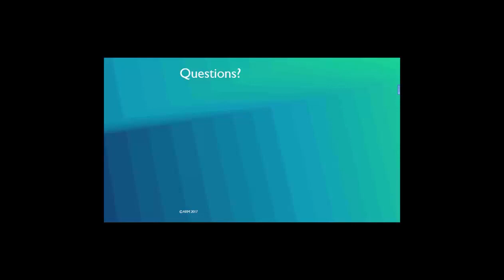Yeah, it's a very good question. So yes, you can split the problem up, kind of standard formal assume-guarantee kind of method. As you say, you can fake out the intermediate state between two instructions with a kind of handwritten piece of prediction logic. And then you can have a different configuration where you forcibly turn off the processor's ability to fuse that instruction. And then you verify that your handwritten model of the intermediate state between those two instructions was in fact correct. And then that gives you a tight solution. Does that make sense?